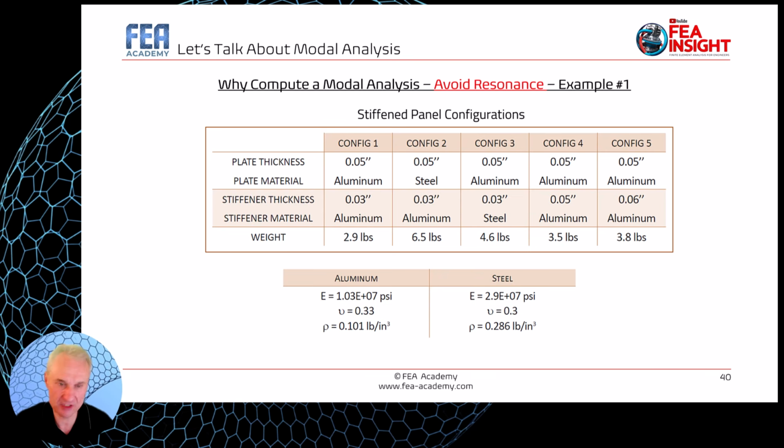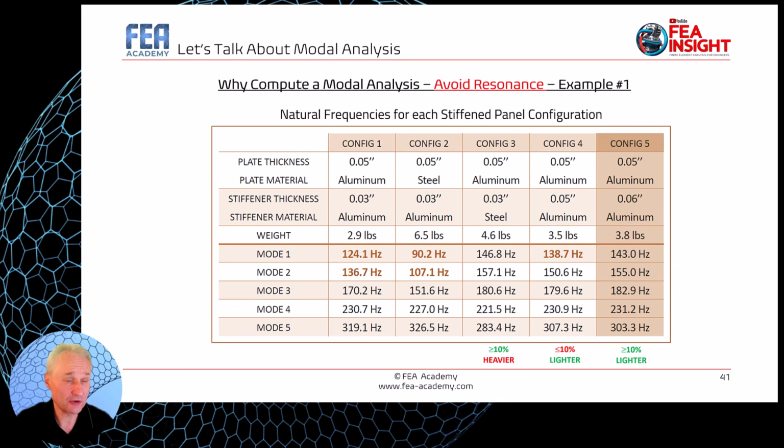Here I am using the Nastran solver, but all the commercial FEA solvers can do this normal mode analysis, in order to compute the natural frequencies with the associated mode shapes. So here are the results I obtained, you see, for the 5 configurations.